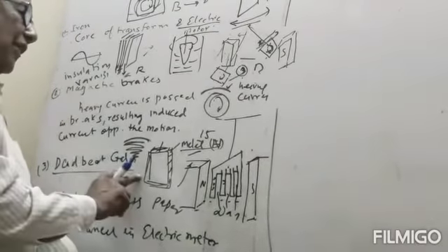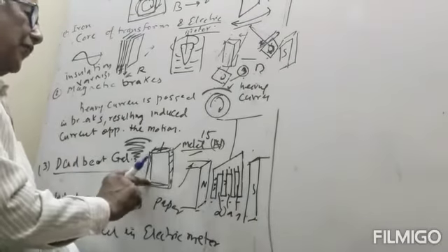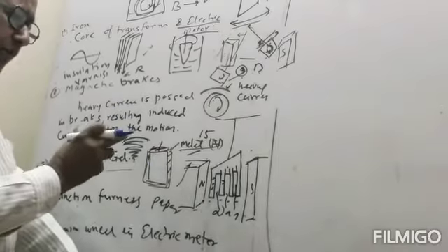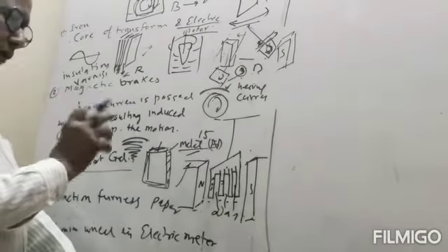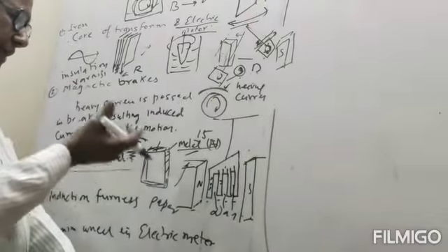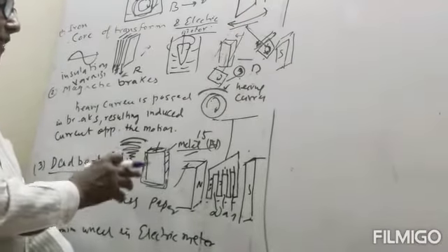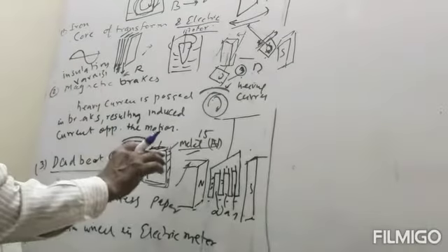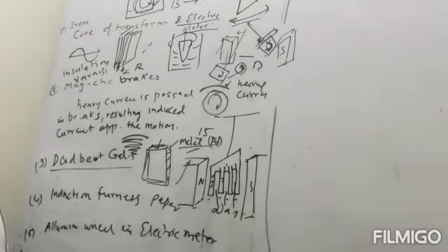But for the instant deflection, what do we do? We will have a metallic frame. In the metallic frame, when the current is passed through it, then it will rotate, then magnetic flux will change, induced currents or eddy currents are produced, and eddy currents will oppose the motion, and it will stop, and we will get the constant deflection within microseconds.